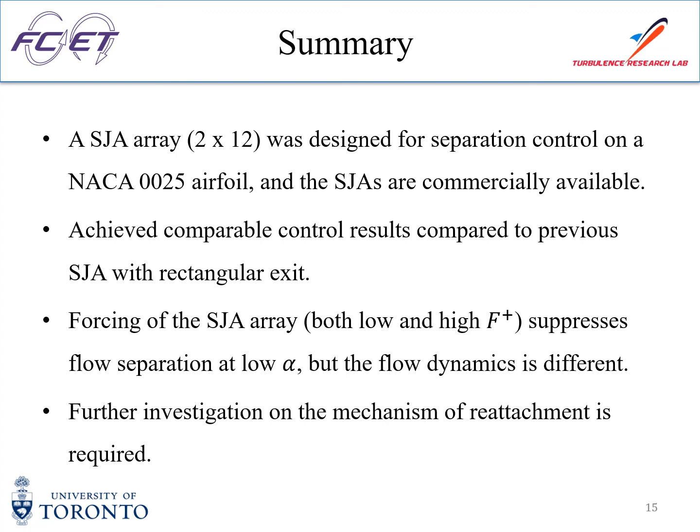And the forcing of the synthetic jet array, at both low and high forcing frequencies, suppresses flow separation at low angle of attack. But the flow dynamics is different, and we need further investigation into the mechanism of the reattachment to find why both forcing frequencies can suppress flow separation.